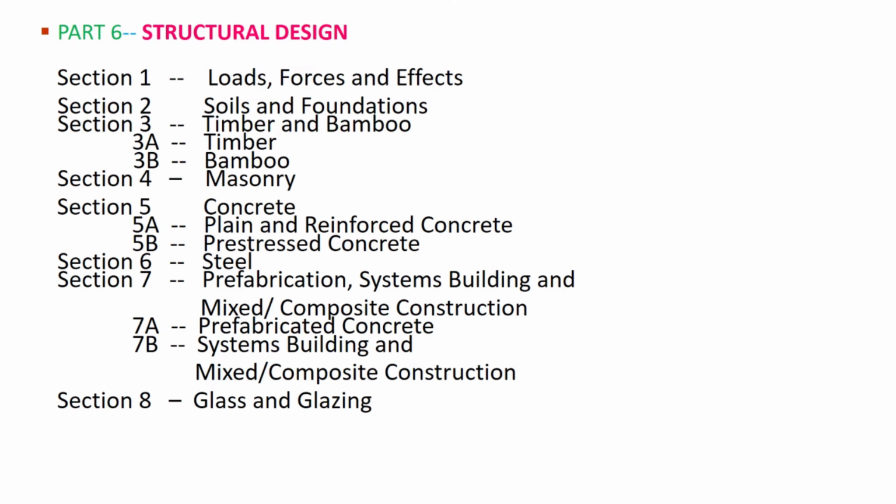Now there are some other occupancies also, maybe some educational buildings, there could be an institutional building too. Except for nursery school, as educational buildings are called, the open space around the building shall not be less than 6 meters. There will be no open space less than 6 meters in front of an educational building. It could be a school, or institutional buildings. Again here it is not less than 6 meters.